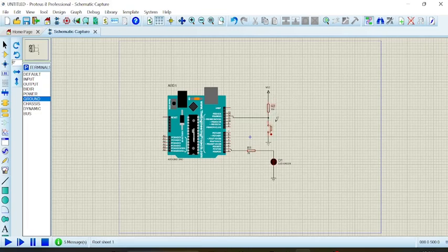We also have the pull down mode. You simply interchange the resistor, bring it down, and the push button bring it up. The pull up mode, when you supply as such, you see that this terminal at pin 12 of the microcontroller will be high because of this 5-volt VCC. Whenever you press the push button, rather than current flowing to the pin of the microcontroller at pin 12, since it is at high impedance, it will prefer to flow to the ground since the ground is at low resistance whenever you press.